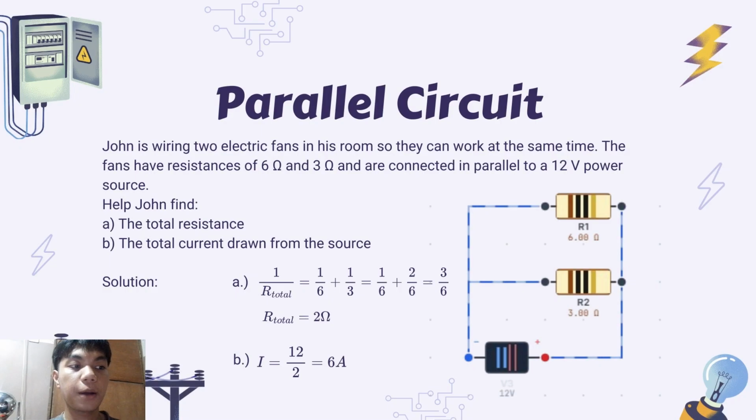So for our next problem, it says that John is wiring 2 electric fans in his room so they can work at the same time. The fans have resistances of 6 and 3 ohms, and all of them are connected in parallel to a 12 volts power source. Now John is trying to find the total resistance and the total current drawn from the source.